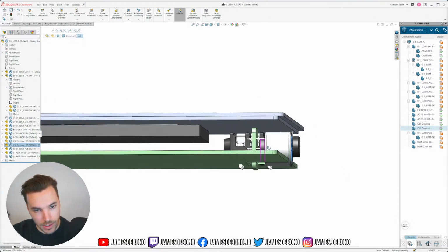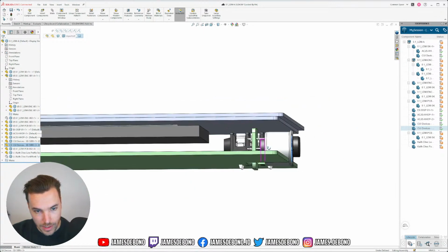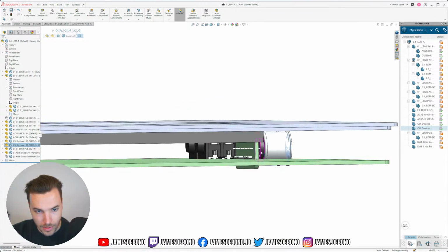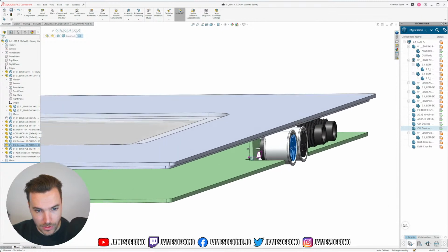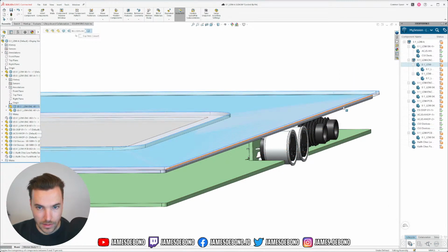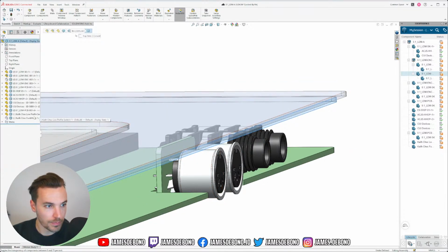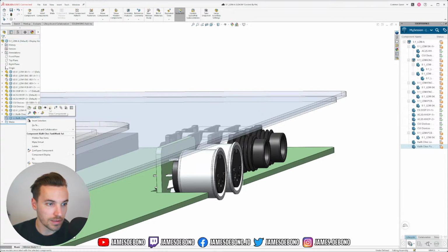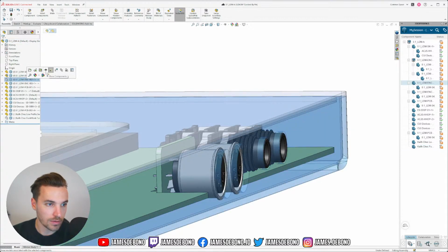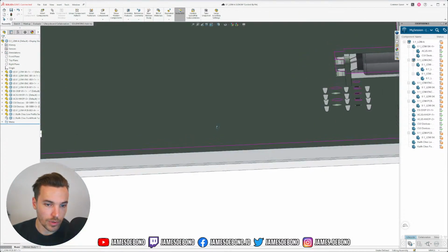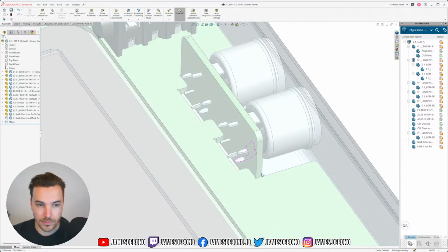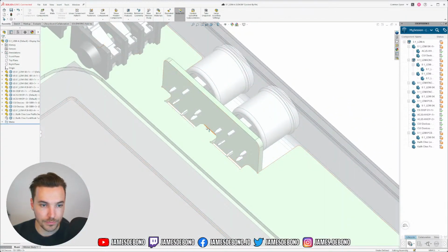I still need to work out how to get the connections from these jacks on this PCB onto this one. And there's basically two ways I'm thinking about doing that. Sorry, I'll just show this again. One of them is that I can just have little contacts on both these PCBs, and you could just put a dob of solder in the corner just to connect them.